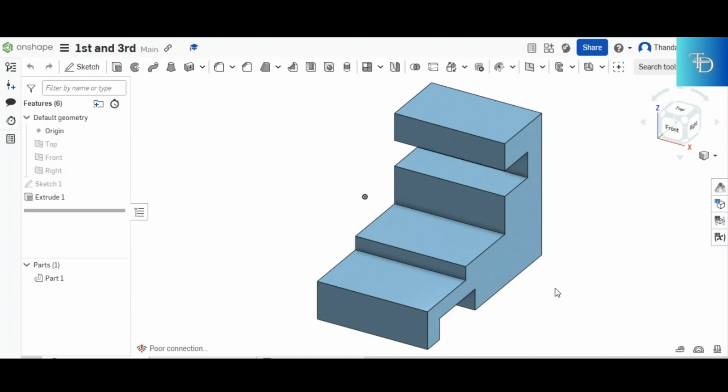So in order for me to say left view and the front view, where am I going to be labeling the front? This is going to be your front view now. Because in order for you to see the left view, you're going to have to see the front right there, and then on the left hand side of the front you see the left view right there. So this is going to be your left view and this is going to be your front view in a first angle. But it depends on the isometric view that is given to you and the projection symbol that goes along with it. That's how you interpret the whole thing.